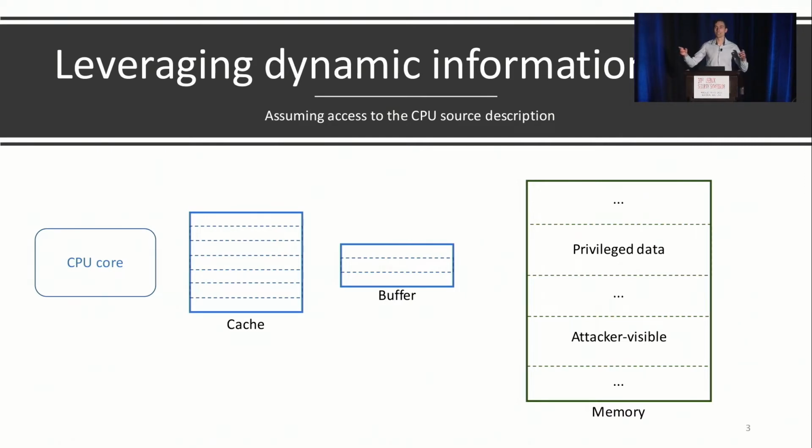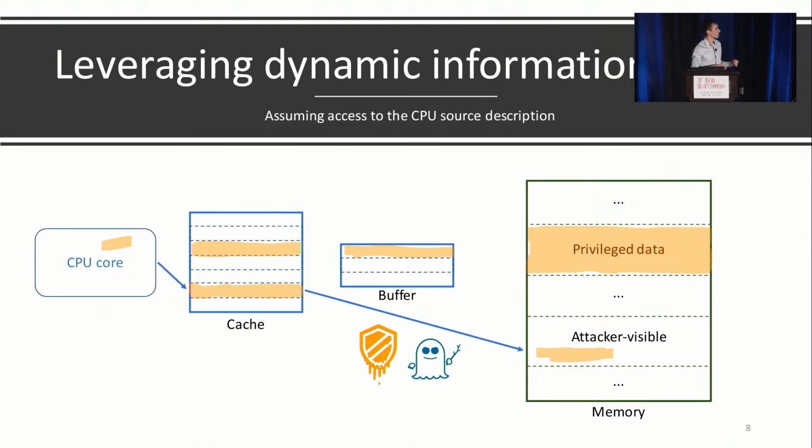So let's assume the CPU does a load from some privileged data that I first tainted. The data, along with the taint, traverses the microarchitecture to finally influence some state in the core. And now if an attacker exfiltrates some data, it will be quite easy to find in principle. You just look: is there some orange taint where I did not expect it? So this is something that we want to achieve.